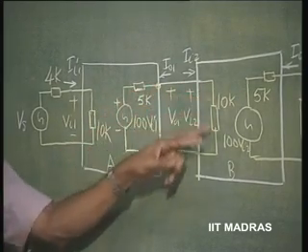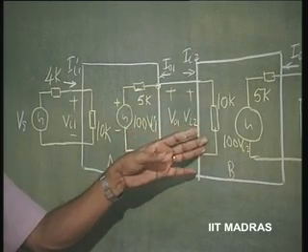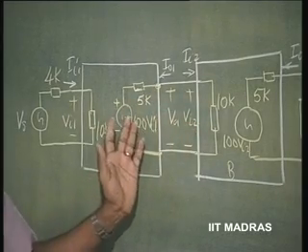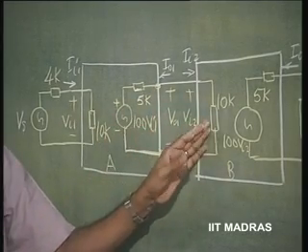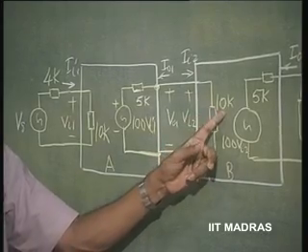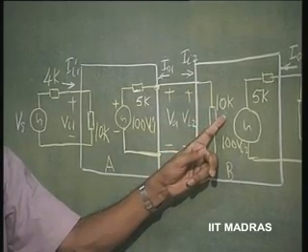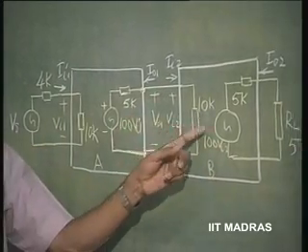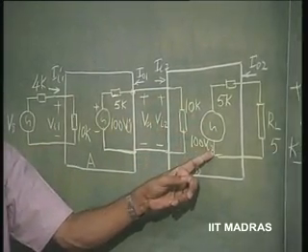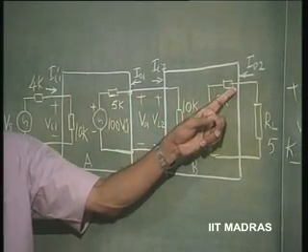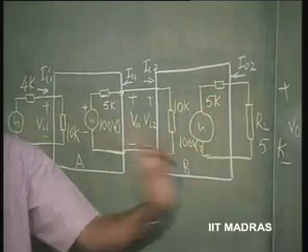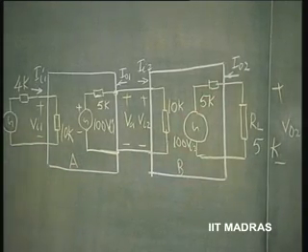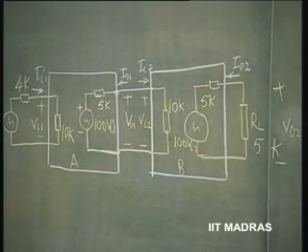It is connected to another amplifier. The load for this amplifier is going to be the input resistance of the next amplifier. So that is 10K. And it has a gain of 100 times Vi2 as the open loop gain, a series resistance of 5K and a load resistance of 5K. This is the pictorial depiction of the problem.